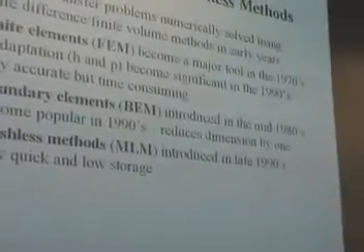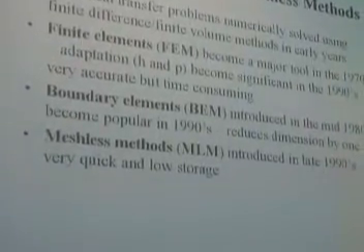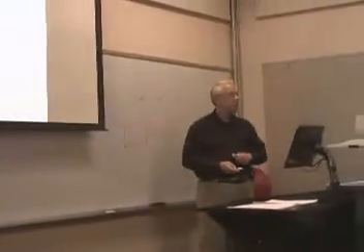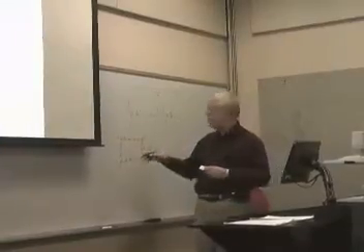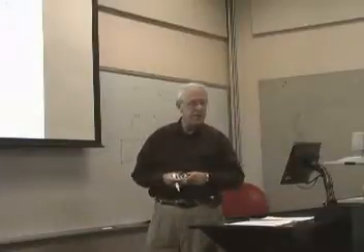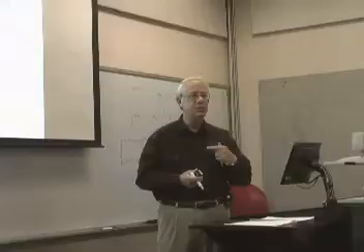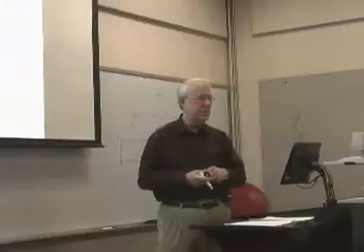All the interior mesh goes away. The only thing you have to do is to set up your node points on the boundary, whatever the boundary would be. That's all you do. You establish the nodes on the boundary, and you can use what's called the boundary element method to give you the same solution accuracy as you got from the finite element method, but with significantly less computational work. That requires one more method of residuals approach beyond what you did for the finite element. Just one more mathematical catch to it.